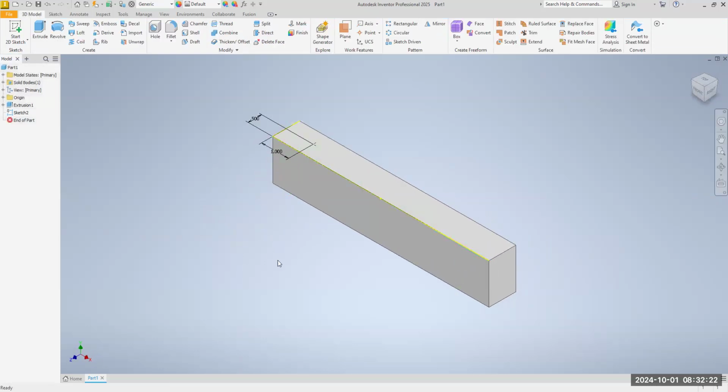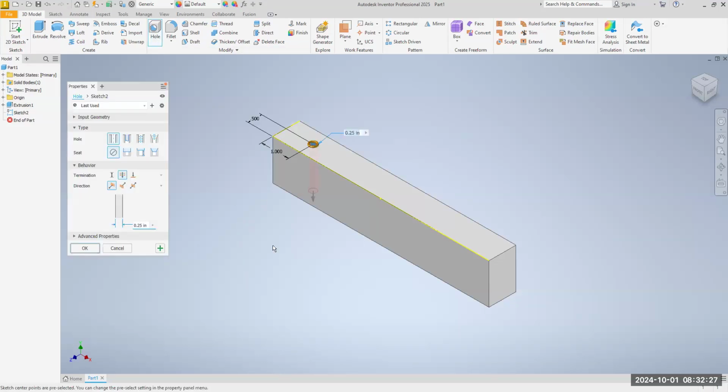All right, now we want to go to hole. I'm going to make a slight modification to this one. If you look on the drawing that I gave the face-to-face class, you will see the hole goes down 0.875 or 7/8 of an inch deep. I'm going to change that to 0.75. So where it says hole, I want you to select simple hole. I don't want any seat.